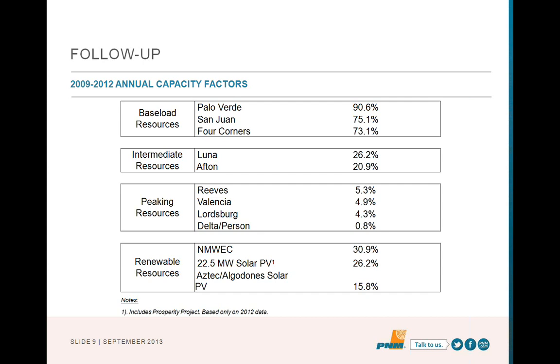So when is it needed? It's needed on summer peak when the load runs up. It's also needed when there are quick changes in the supply-demand balance. An example of that would be the Super Bowl at halftime. This is a water example, but at halftime the water demand on the system goes way up. You can end up with situations like that on the electric system also. We have to keep the electricity supply and demand in balance all the time, so we have peaking capacity that helps us do that.